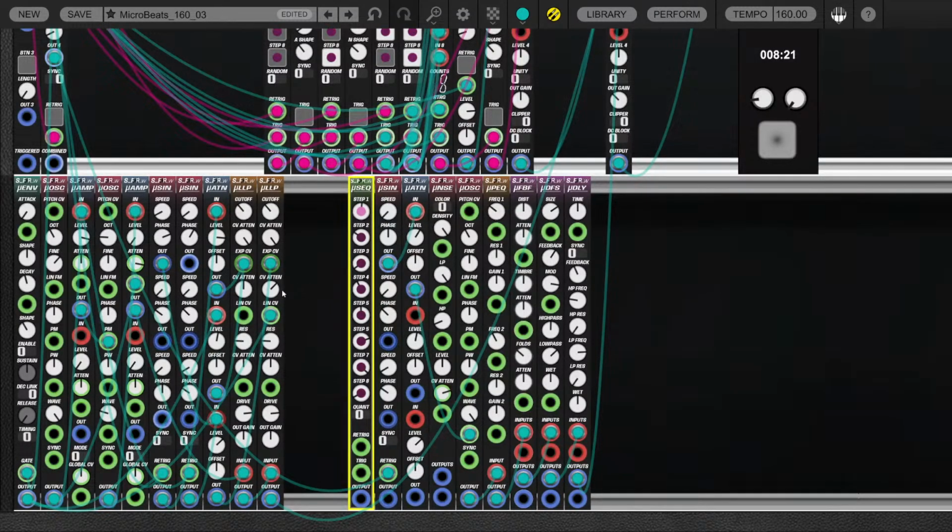So you go from a 10 octave range to a 2 octave range, which can be more sensible for pitch CV or for smaller modulation. And you also have the quantized modes, so it is quantized to semitones in the -5 to +5 volt range or in the -1 to +1 volt range. So you get already a lot of control over the pitches or the CV you can set.